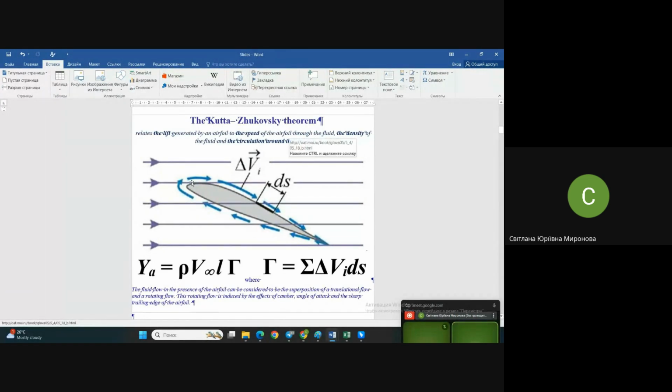These formulas, in contrast to the simple and understandable formulas for lift and drag that you have seen before, are rather difficult to understand, and it's difficult to imagine what they are about. Such a formula for lift states the relation between the density of the medium, the density of the flow, and the speed of the undisturbed streamlines, so-called, which comes from some place where the profile is not intruded yet, the length, the perimeter actually, of this profile, and the so-called circulation of velocity along this profile.